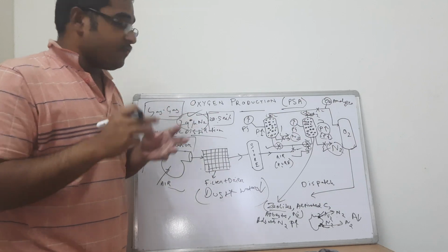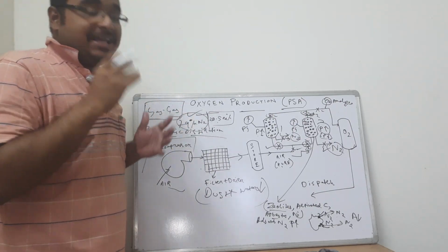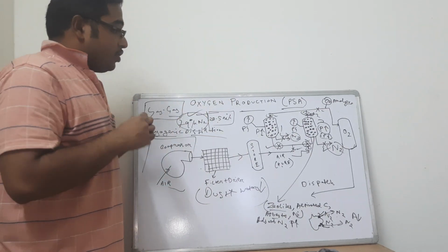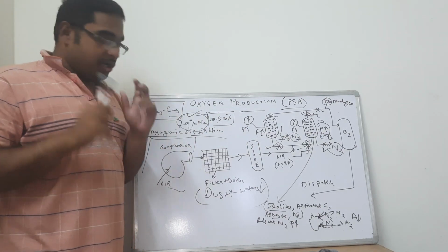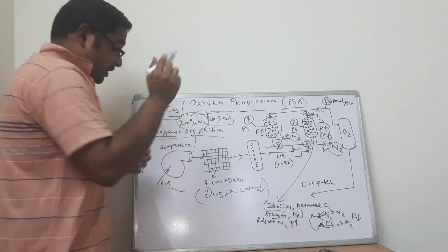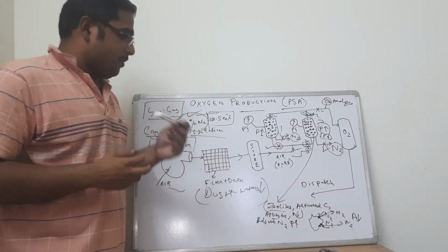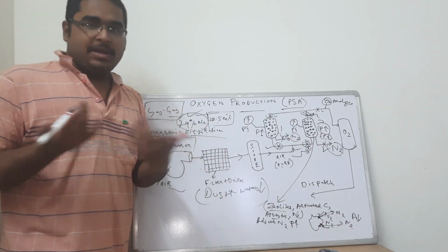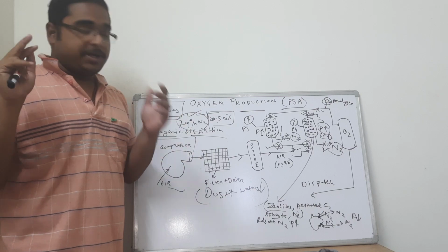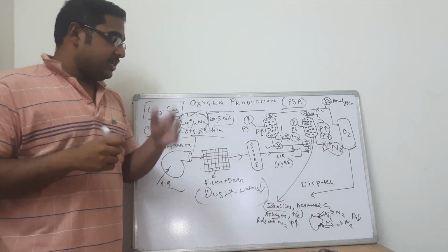You can use ceramic balls for packing, and in between you can keep the zeolite bed such that the gas evenly gets distributed and the nitrogen is trapped on the zeolite structure. So you see, this packing bed is not difficult to manufacture. This compressor is easily available in the market. This filter press dryer is easily available in the market. These storage vessels can be made available in the market. And finally, the dispatch is directly connected to the hospital oxygen line, or it is sent to a bottling plant wherein bottling of oxygen in oxygen cylinders takes place.